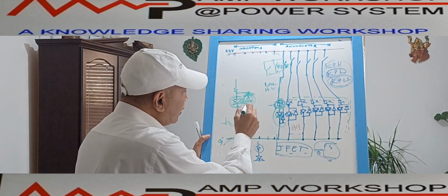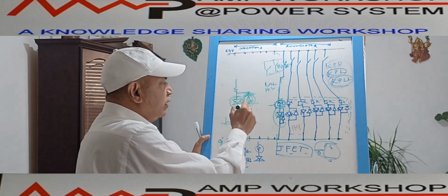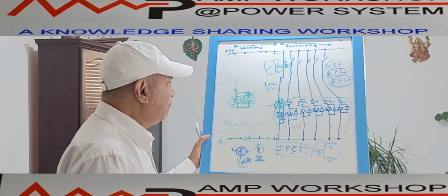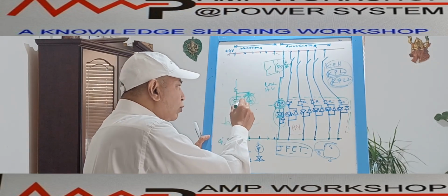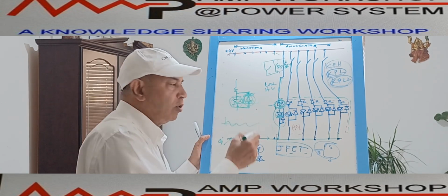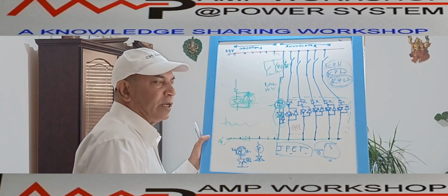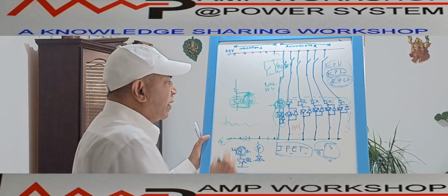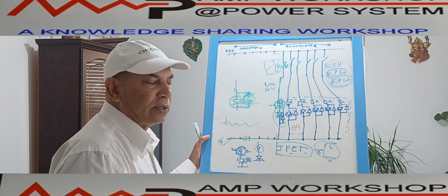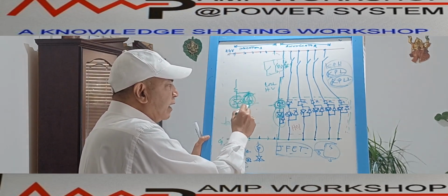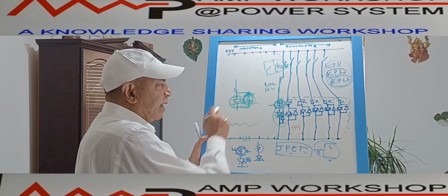Second, all this damping current is passed through the reverse bias diode. Another, if there is suddenly an over voltage, then immediately, to suppress that over voltage, this reverse bias diode operates. So the reverse bias diode will operate on over voltage and it will protect this diode, these LEDs. That is another function of the reverse bias diode connected in parallel to the LEDs.